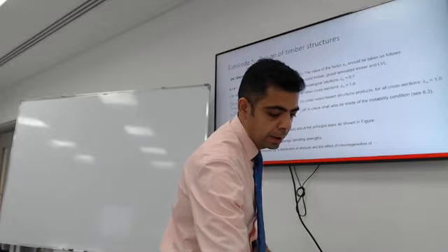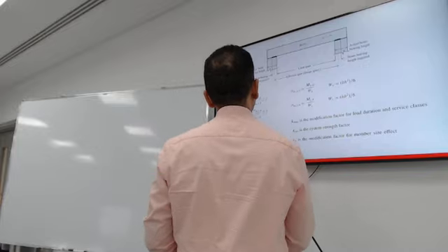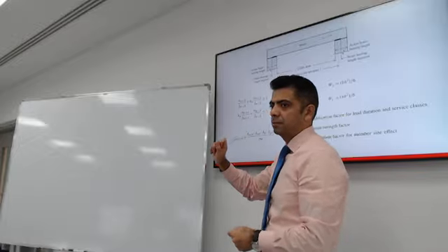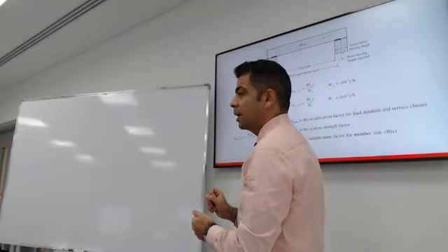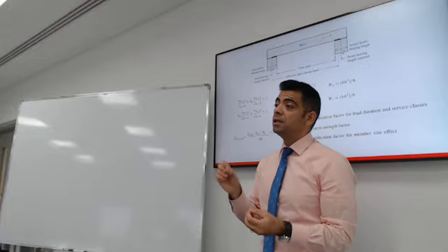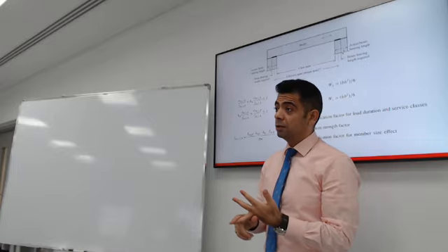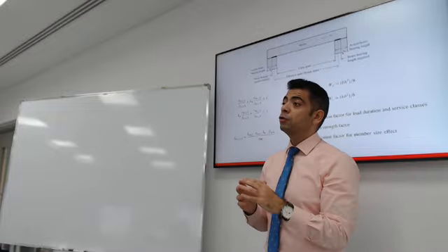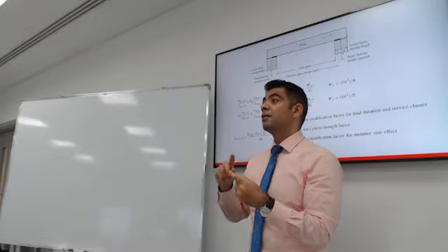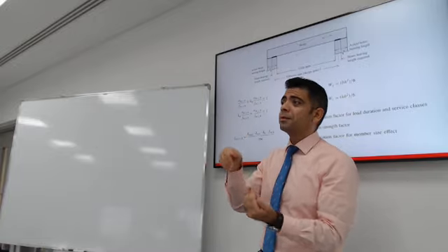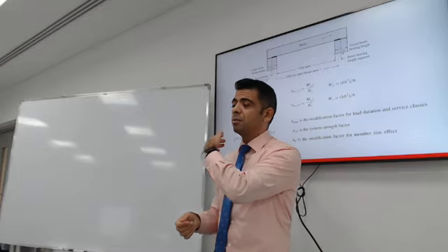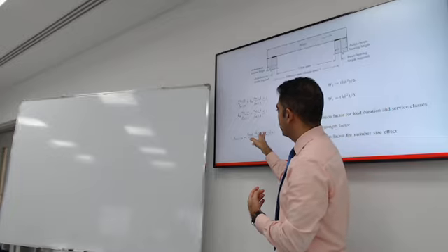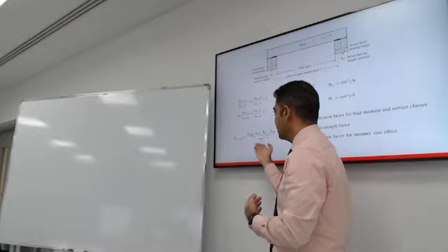All right, so let me walk you through what actually goes into calculating the maximum stress that wood can take. How do you get the maximum stress that wood can take? First, I need to know what species of wood, what is the grade of wood, and then the code will help us use some guidelines and assumptions for the modulus of elasticity for this grade. The maximum stress parallel to grain, maximum stress perpendicular to grain. And I have this table, I will share it with you. So this is how we're going to get Fm. But we need to take 3 other things into account and a material factor of safety.